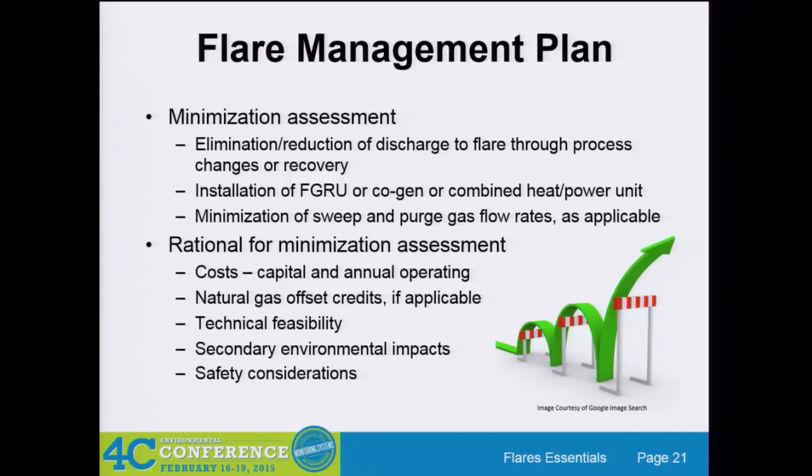Why should we put in flare gas recovery if we can't use the gas? And the rule writers decided to say, nah, you can't pull that one on us. You also have to consider installing cogen with your FGR to burn that gas and create electricity with your excess gas. So you have to assess it. Hopefully, if you don't want to spend a lot of money, it's not feasible.